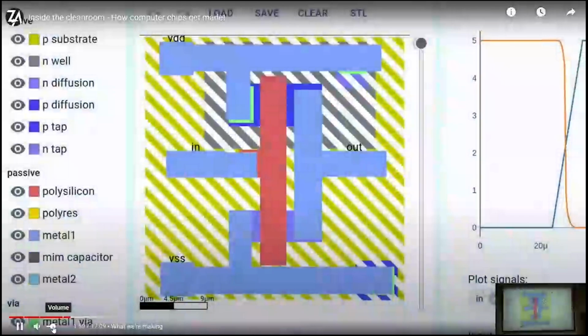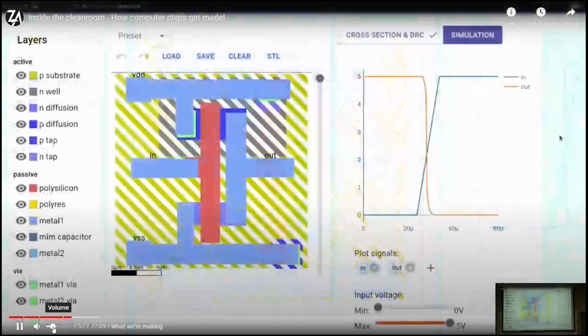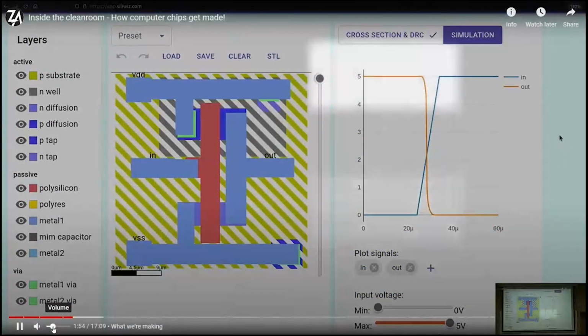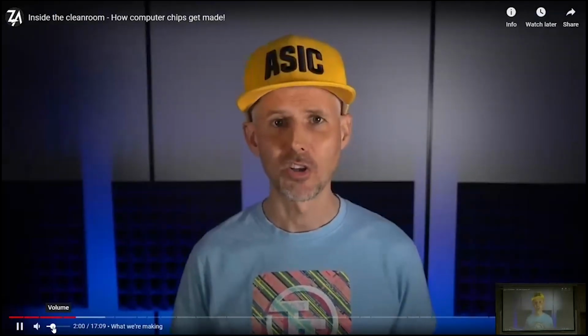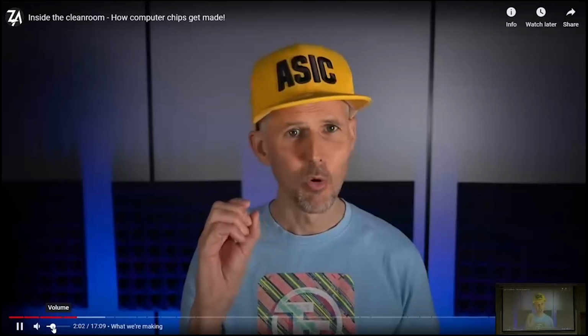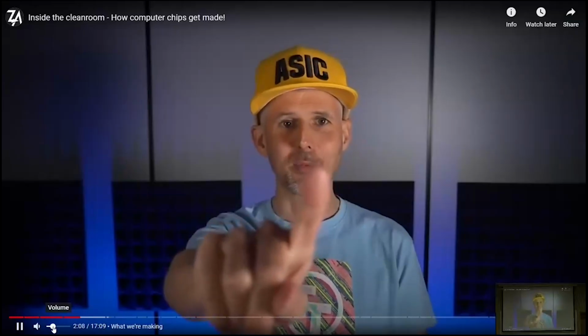Here's one of the simplest gates, an inverter. When the blue input is low, the orange output goes high. It works by using a pair of switches called MOSFETs. They don't have any moving parts, so they can be made incredibly small. At IHP, they make the MOSFETs so small that you can easily fit 10,000 across your fingertip, or 1,000 if you've got very tiny hands.